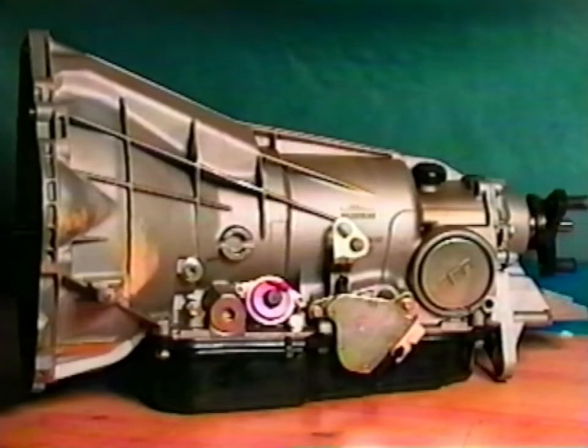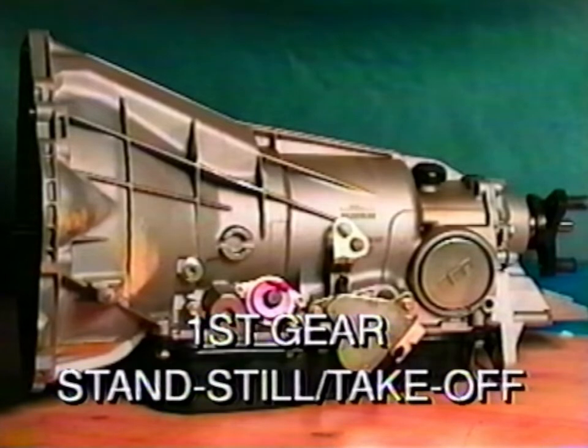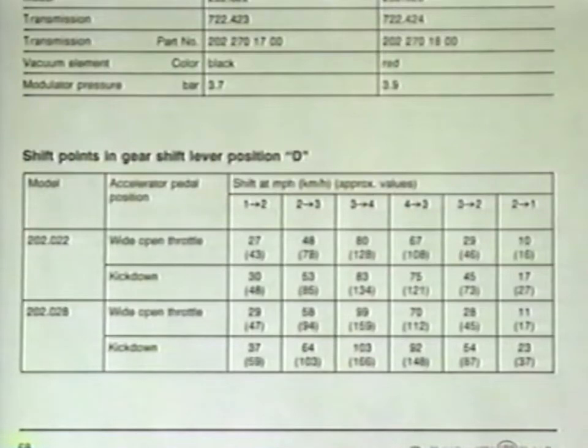The automatic transmission used in Model 202 is the familiar type 722.4. The transmission engages first gear at standstill and on takeoff. You'll find a shift point chart in the introduction manual to assist in diagnosing shift point complaints.